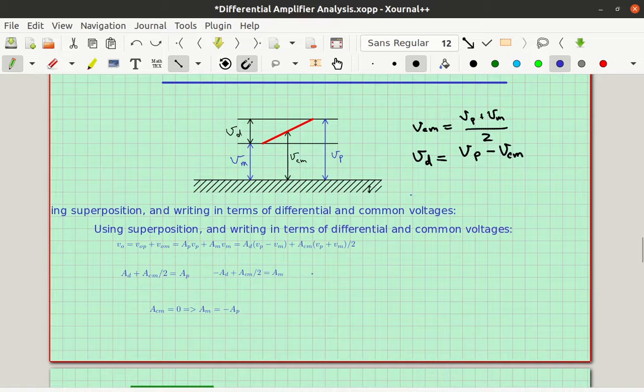So voltage is like height. And when you have two voltages, one for each wire, you can describe it in two ways. One for the first wire, maybe we call that VP right here. That's this wire. That's the normal way of doing it. That's the voltage between VP and ground. In other words, the height from this top line right up here to ground down here. And to describe the other wire would be VM. That's this guy right here, which gives us the height from the lower height to ground.